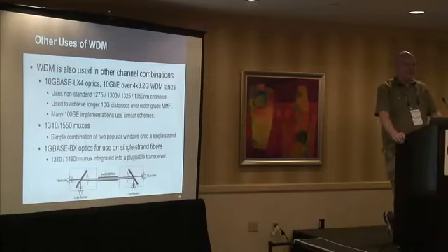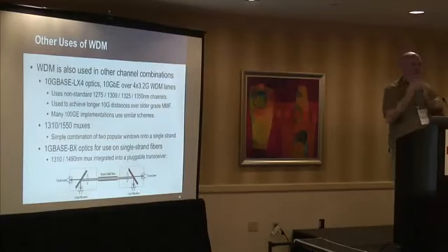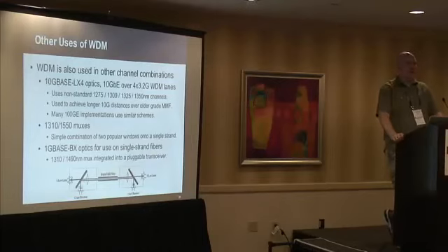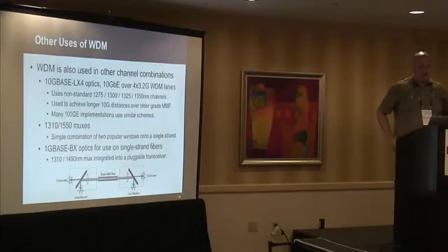It had some advantages for certain technology like Xenpak, which actually talks to the router, talks to the optical via four lanes anyway, so it's really easy for the box to take those 4 things, turn it into 4 different signals, put it in a little tiny mux that's actually integrated into the pluggable. These days you're going to start to see that for 100 gig. 100 gig optical, pure optical, just doesn't exist, or it exists in the lab. It's not practical. You can't do any distance with it. So what you see out there is a lot of 4x25 or 10x10, things like that.